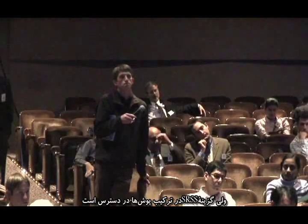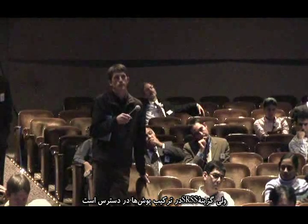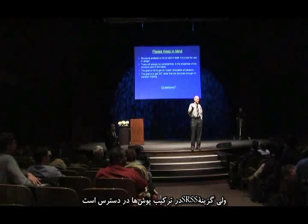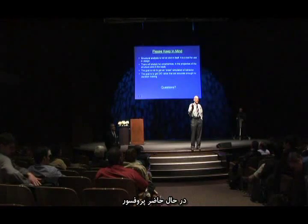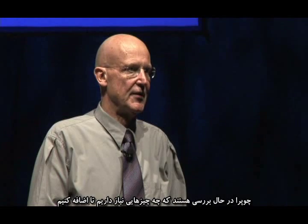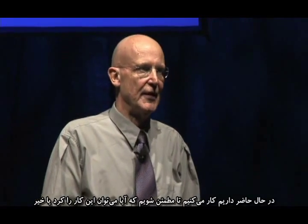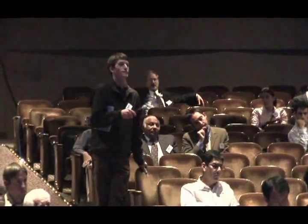I think so, and I'm not certain because there's no CQC option in Perform, but there is an SRSS option available in the envelopes combination task. And I'm currently working on it with Professor Goel and Professor Chopra to see if there's anything else we need to add. So right now we're working on it. I'm not certain yet whether you can do it or not. Thank you.